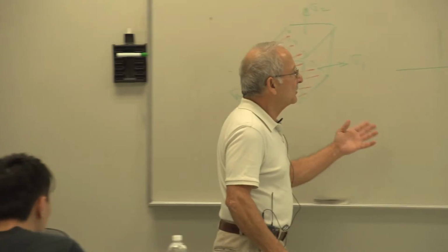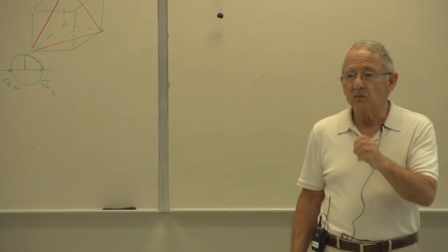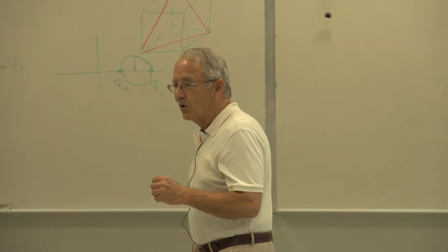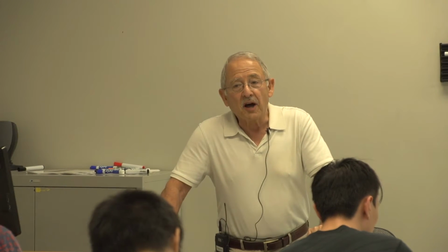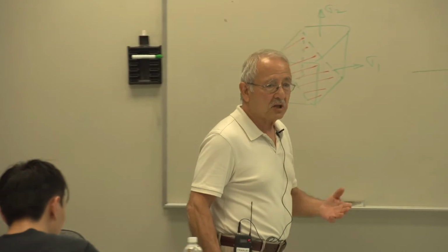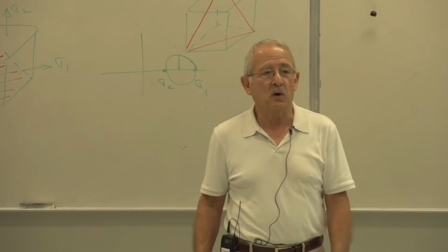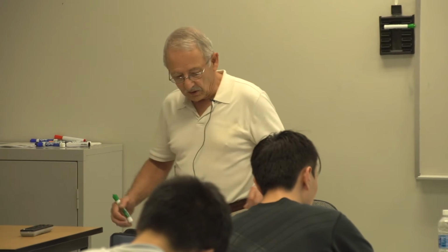It does exist. And the answer that you get from this failure theory, the octahedral shear stress failure theory, is exactly the same as that which you find from the von Mises. So if you're trying to find something, quote unquote, tangible, insofar as the von Mises stress is concerned, this is it. But of course we don't use this in real life because although it's possible to find the shear stress on that plane, it's not a very friendly thing to do. So rather than doing that, we calculate the von Mises stress, which actually is not a real stress in the material, but gives us the same answer anyway. So if you're looking for something that actually exists, that's it, the octahedral shear stress.